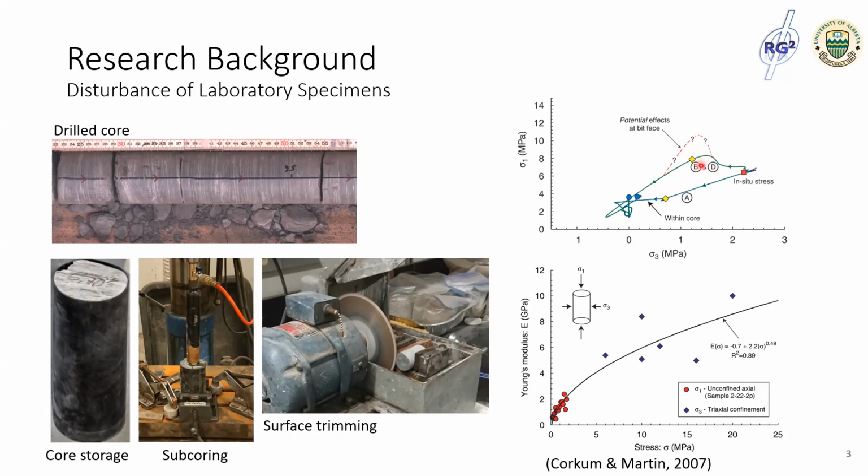So modeling studies on Opalinus Clay show that a specimen may suffer from a very complicated stress path from its in-situ state, and the laboratory tests on the Opalinus Clay, even for specimens from the same borehole, show high variability of measured Young's modulus. Therefore, we think it would be nice to employ an in-situ testing technique as a less disturbed method to improve the assessment of the intact geomechanical properties of the ground.